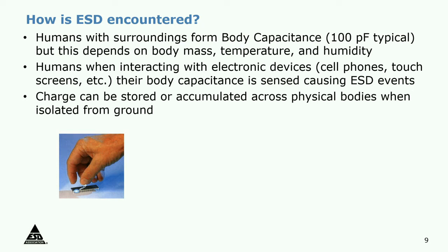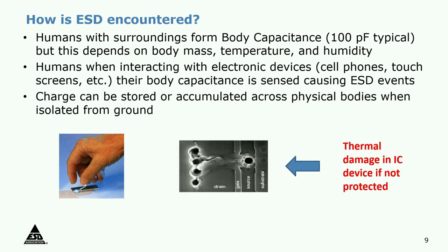And while that energy is very small, in microjoules, it is enough to damage a transistor. As you can see, the damage is from drain to source of a MOSFET that has blown across. So a certain level of potential from the human body can destroy a pin.